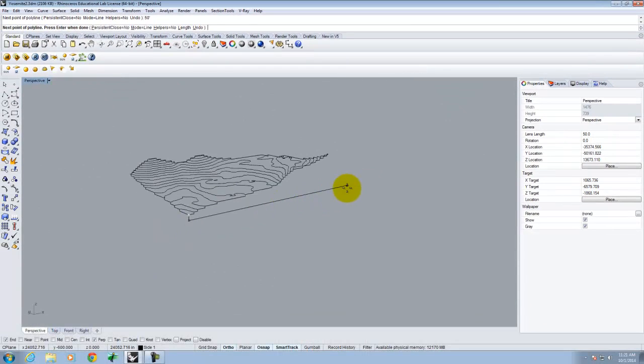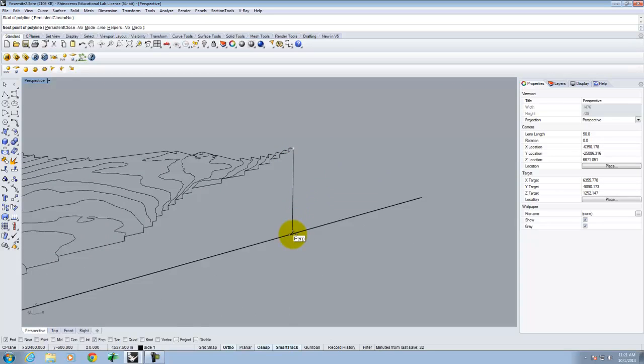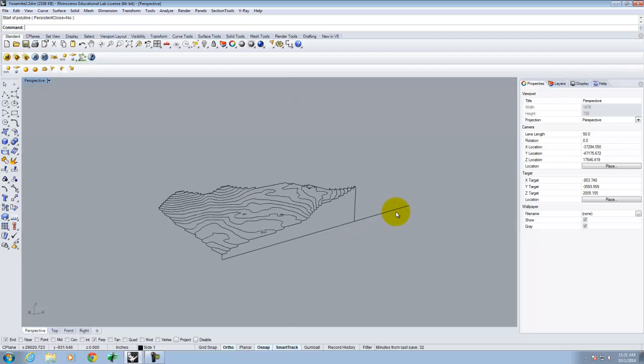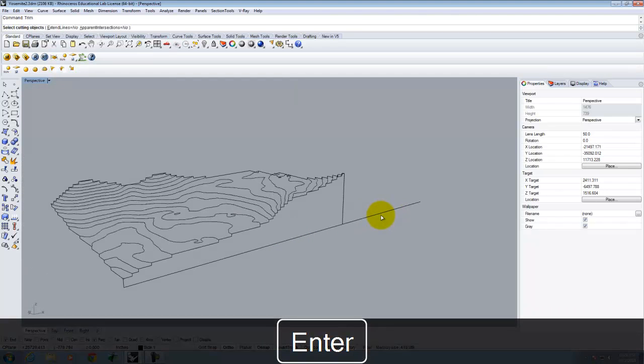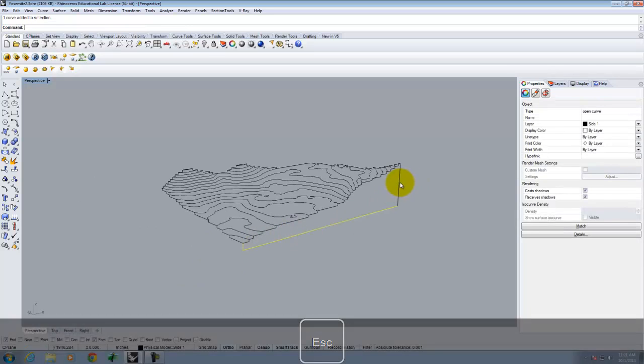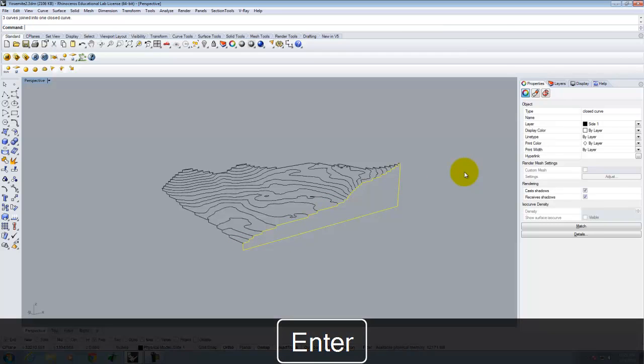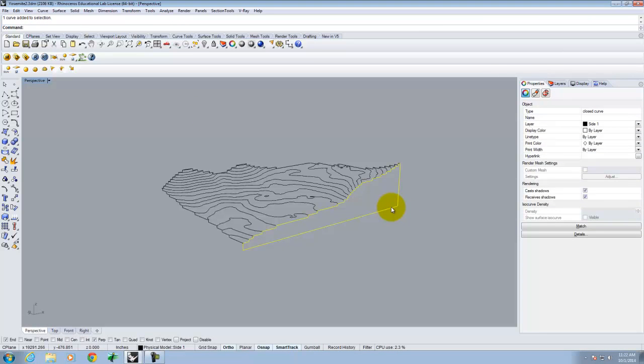Now I'll go ahead and draw a side that extends off in that direction, and I'll come back and draw a line down perpendicular to meet there, and then I can go ahead and trim off that piece. Sorry, my head's in the way. And so I'll end up with one side, right? There's my pieces and there's my top. So let's go ahead, for clarity purposes, and join that together. 3 curves joined into one closed curve, and I now have a complete side for one of my models.